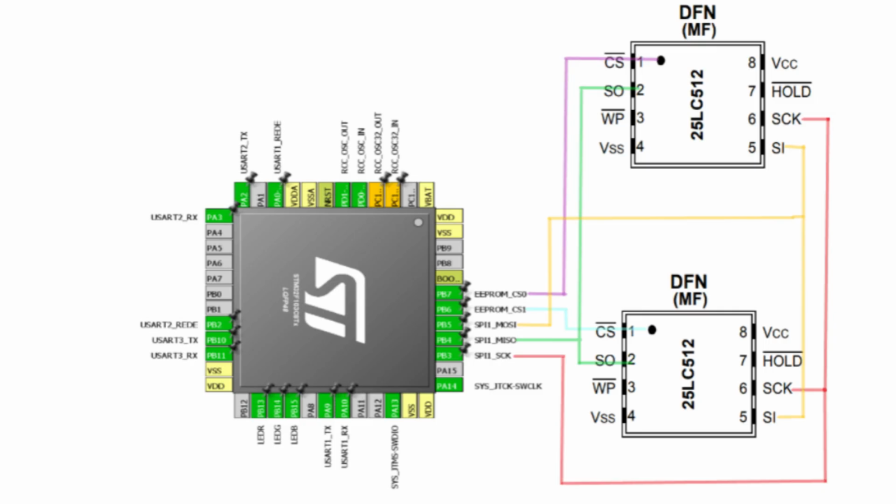Second, signal integrity. Keep PCB traces for SCK, MOSI, MISO, and CS short and direct. Avoid routing them near noisy components like switching regulators. Use a solid ground plane underneath. Consider small series termination resistors, 22 to 33 ohms, on SCK and MOSI placed near the STM32 master to dampen reflections, especially if traces are longer than a few centimeters or speeds are high.